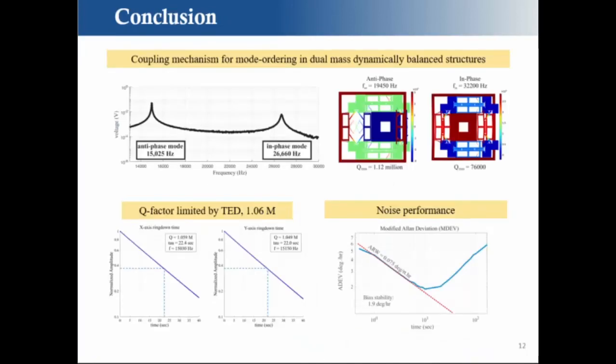So this is the conclusion. Several things were demonstrated: we introduced the concept of mode ordering, and we showed that the concept does work, where the antiphase and in-phase modes are separated and placed in the right order. We achieved a quality factor by design close to thermoelastic damping, and we showed that the device, even in such a small volume, can perform at a very reasonable noise level.